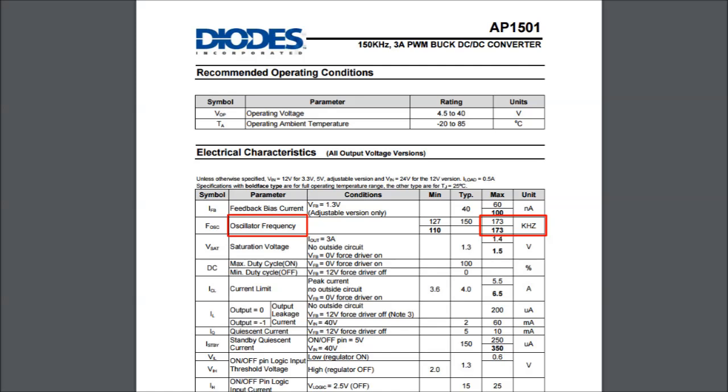I plan on experimenting. This is a video game at 600 frames per second on an LED TV. The flicker is about 2 frames on and 2 frames off, or 150 Hz. The pulse width modulation is still not fast enough to keep up with the speed of the LEDs.